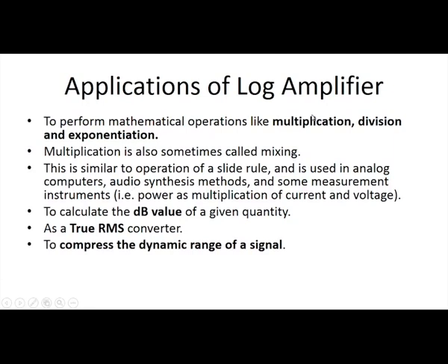The applications of the logarithmic amplifier are that it is used for multiplication, division and exponentiation. The multiplication is also sometimes called mixing, and it is used to calculate the dB value. When you see the frequency response of any amplifier or integrator, just now in the previous lecture we have seen the integrator, in the y axis we have taken the gain, which is in dB.